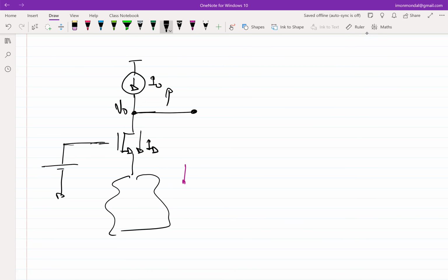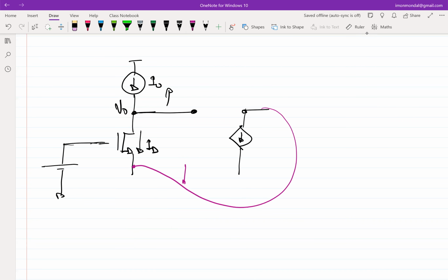So how do I decrease any voltage? I pull current out from that node, right? So essentially, if I just say that I have a control source, and the direction is as I have shown here, I will connect it here and get rid of this stuff. Obviously I haven't shown the controlling terminals here, but the argument will be we have to connect up this control source in such a way that as this voltage increases, this voltage decreases.